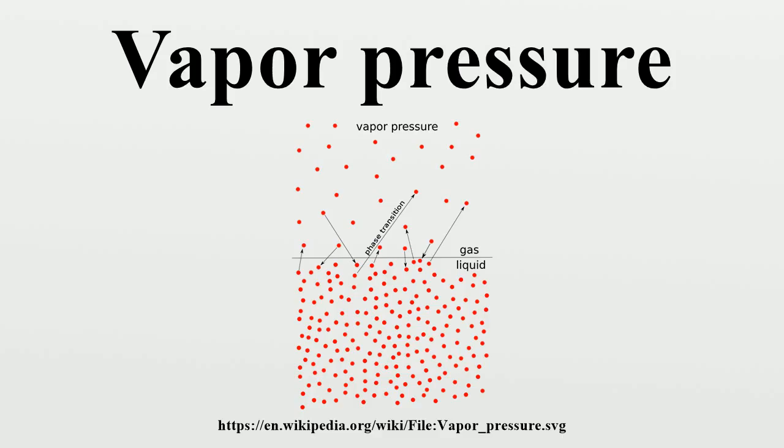Although the relation between vapor pressure and temperature is nonlinear, the chart uses a logarithmic vertical axis to produce slightly curved lines, so one chart can graph many liquids. A nearly straight line is obtained when the logarithm of the vapor pressure is plotted against 1/(T + 230), where T is the temperature in degrees Celsius. The vapor pressure of a liquid at its boiling point equals the pressure of its surrounding environment.